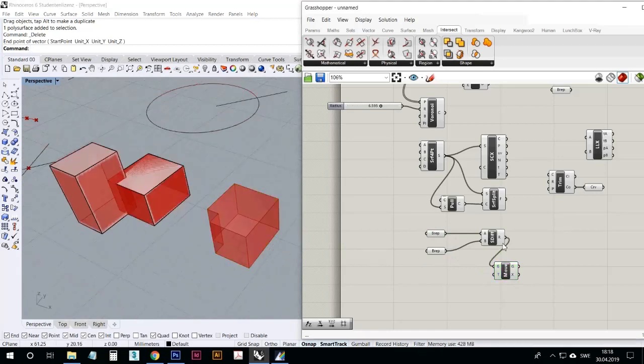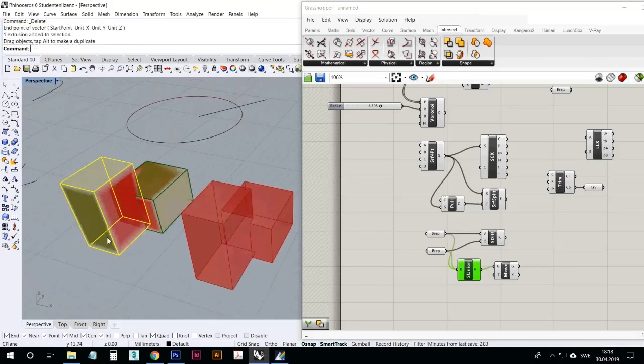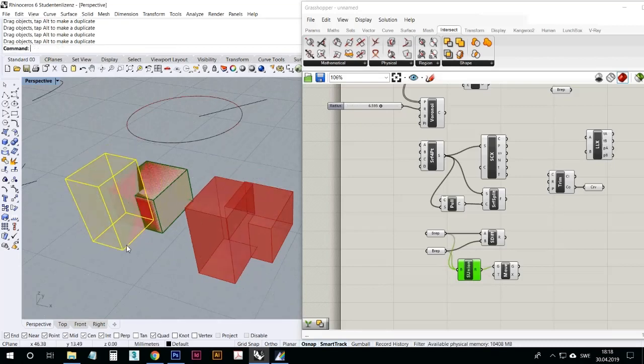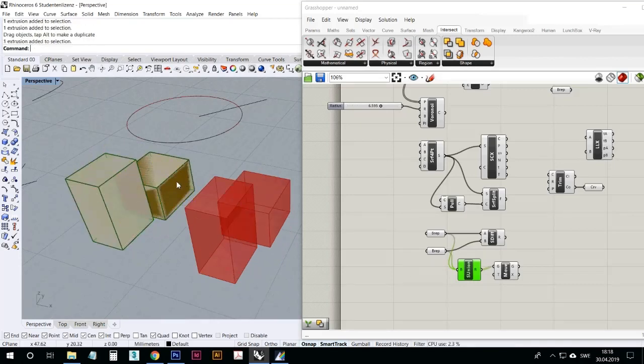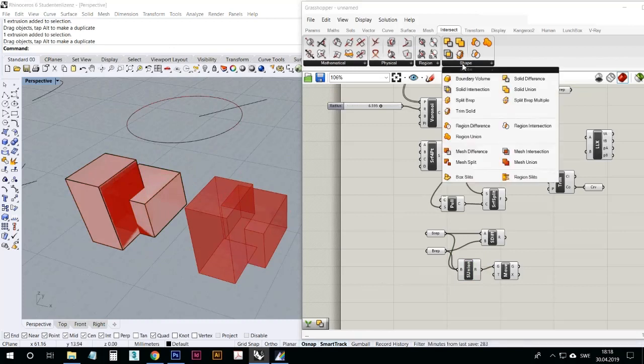We can test another one here, for example. If I just do this and hold shift with both of them and move that instead, you see that that is the result of it. If I move them around, it makes a Boolean union perfectly and parametrically the whole time here, which is quite interesting indeed, isn't it? So they're not intersecting anymore like that. We can also make a split multiple with each other, of course, so you can test these out.